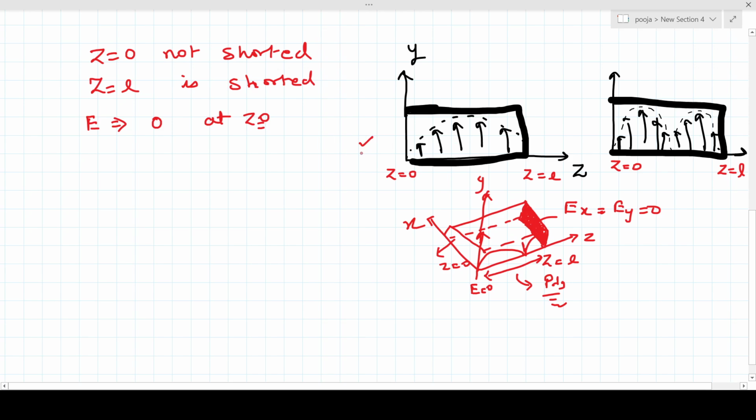So these are two particular cases. In this case, P is equal to 1, and in this case, P is equal to 2. So this length is lambda g by 2. We have two nulls at lambda g by 2. The wave is 0 here, which is scientifically correct. It means nulls occur at each lambda g by 2. Here we have P equal to 2, which means this length L is equal to lambda g, and we'll have two nulls occurring within this particular length.